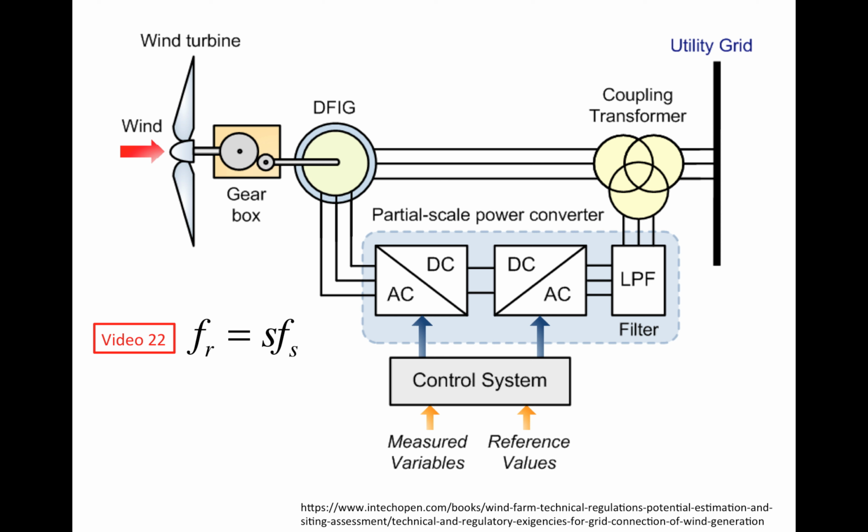The rotor speed can be very high and can fluctuate very quickly. It allows for high slip operation of the induction generator, but it does not allow recovering the excess slip power to a useful form. So for slip power recovery purposes, we will need to replace that external resistor with something called a power converter.